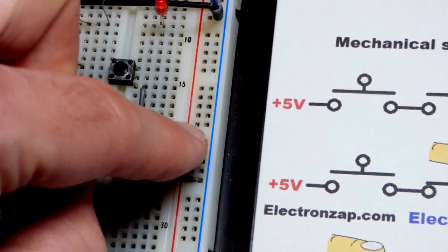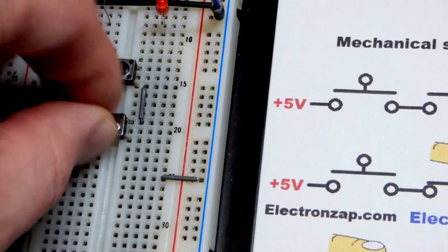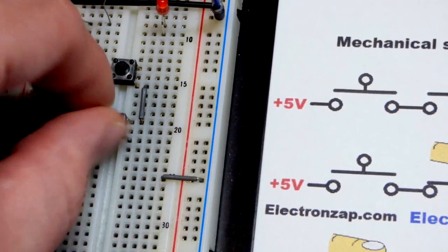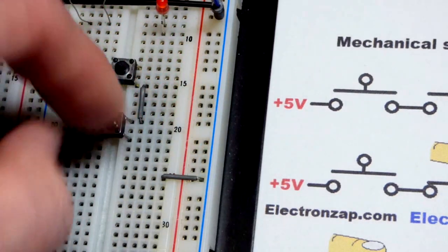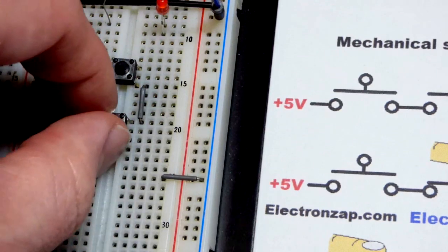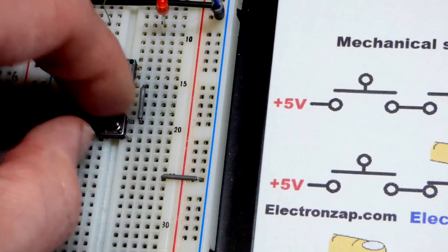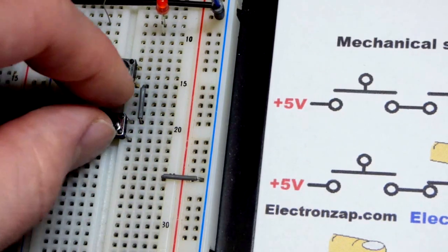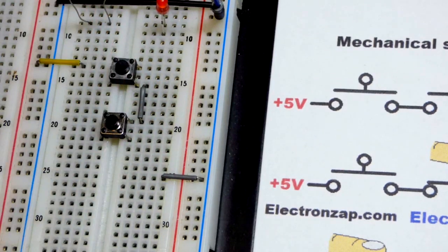Another thing is I usually put the middle of the switches, there's no terminal there, where the gap is on the breadboard for a couple reasons. One, so it's easy to tell where the middle is and where the top and the bottom is. And also because these terminals are a little bit bigger than the wires of other components, so it kind of stretches out the holes, so it helps keep track of where these wired terminals might not fit in very well.